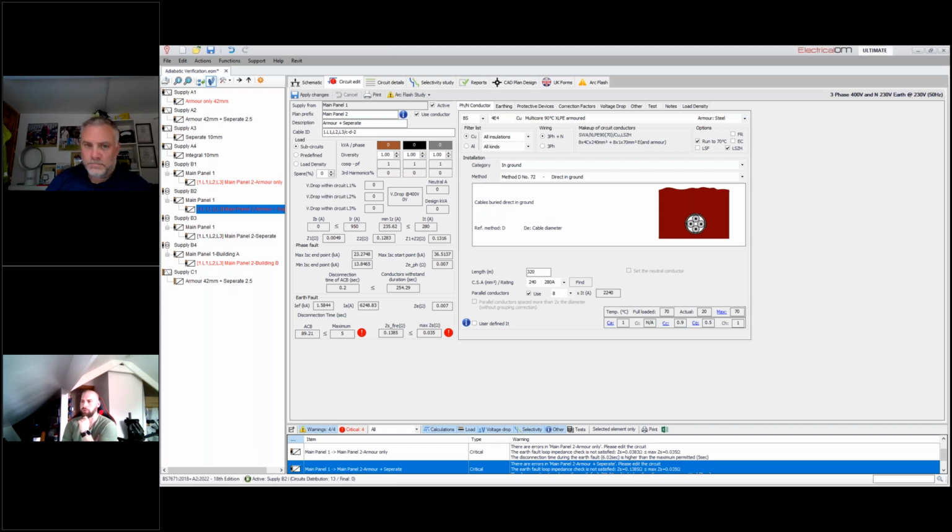You gave an example of 70s and 95s. I mean, the effects at those sizes, if you're only looking at relatively small, so parallel, looking at 300 amps, 350 amps, the effects are going to be relatively negligible, to be honest. Generally, it comes up when you've got much bigger, when you're trying to do large scale site distribution. You will see a slight effect between the two in terms of the possible upsizing of a phase conductor.